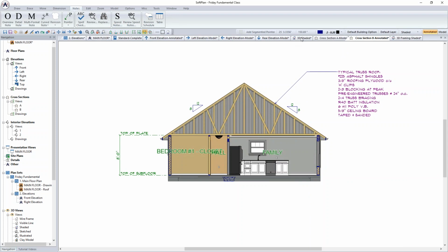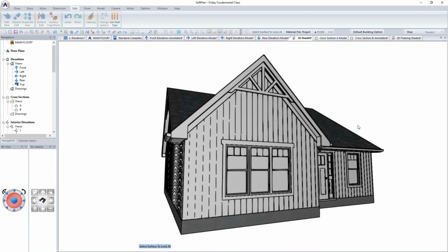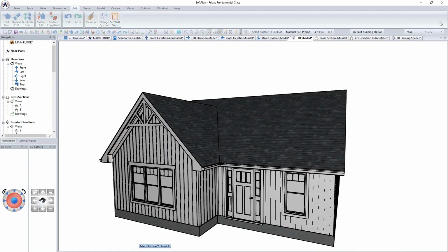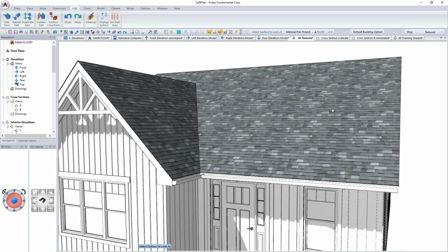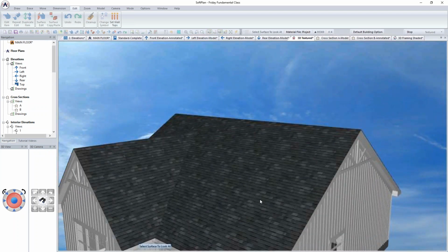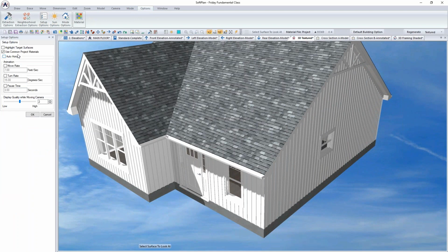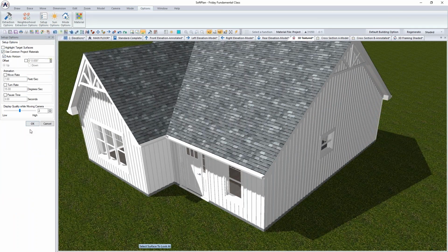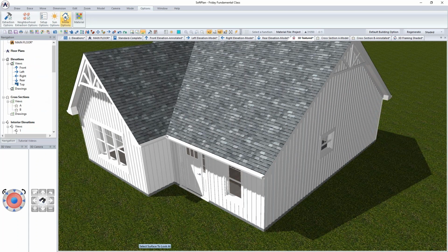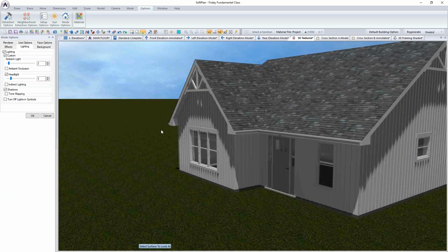And then of course, we have been doing a lot of work inside 3D, which is what we have here. To date we've done all of our modifications inside the shaded. I could then take it to the higher, detailed option of it being textured. This might be where I'm going to go in now under my options and setup options, turn on my auto horizon, and then inside the mode options, this is where I may start getting into customized lighting so that we can actually begin to see the shadows and so on that are taking place with the model.